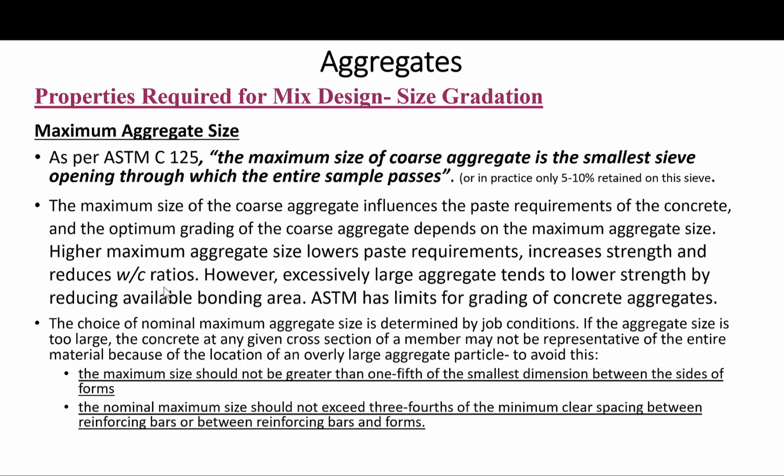Most equipment in the concrete and ready mixed concrete industry can handle up to 50 millimeter or 2-inch maximum aggregate size, but equipment used in mass concrete construction can handle up to 6-inch or 150 mm coarse aggregate, where the larger volumes of concrete justify the use of the larger equipment needed for these aggregate sizes.